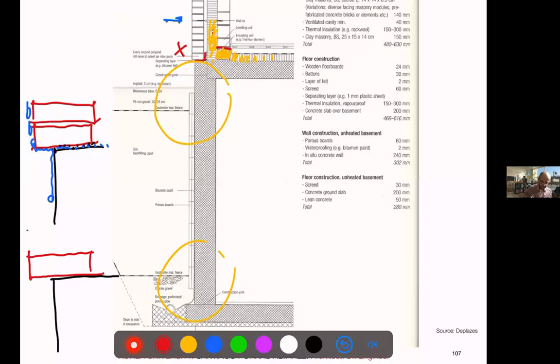In the first brick, and remember, we cannot go out very much. This should be maximum 1/3 of the brick, right? Otherwise it might stumble. Is putting some metallic element, some kind of angle, right? Which actually may help supporting, right? This will be fixed to the concrete. This can also hold the waterproof, let's put the waterproof here, the waterproof layer, right, under or over.